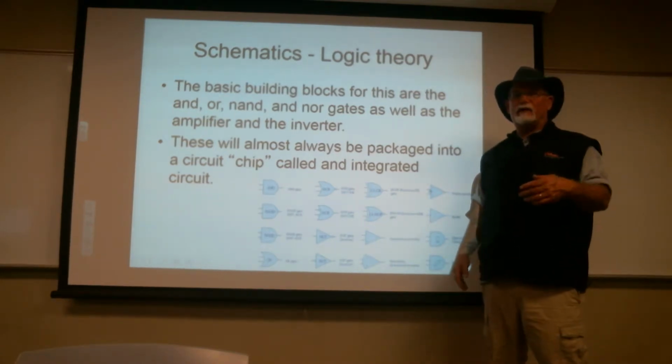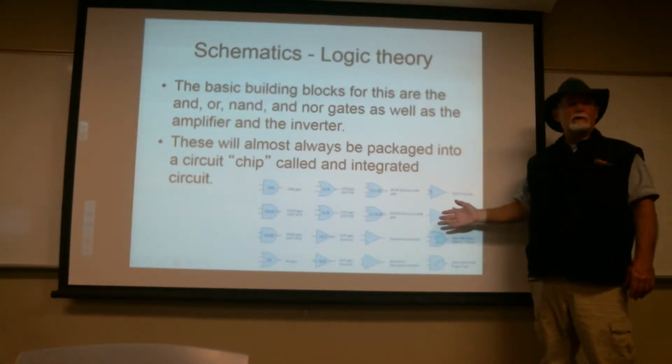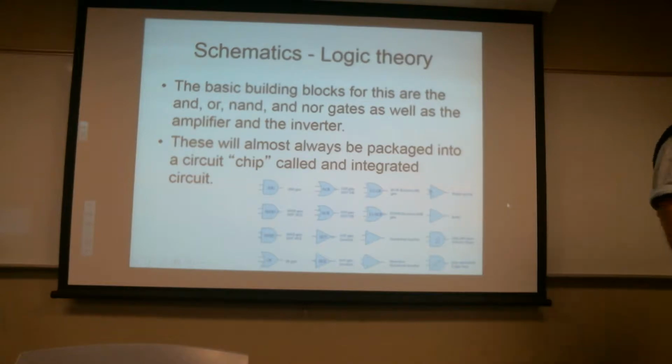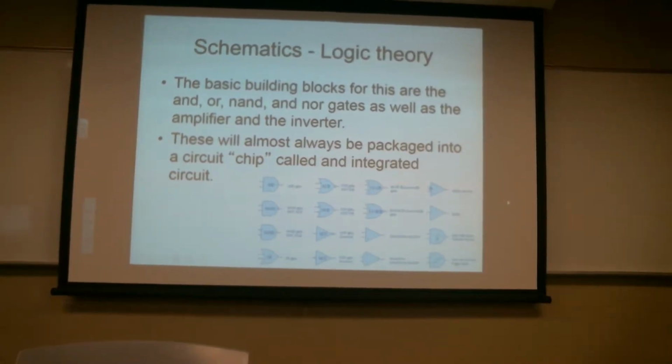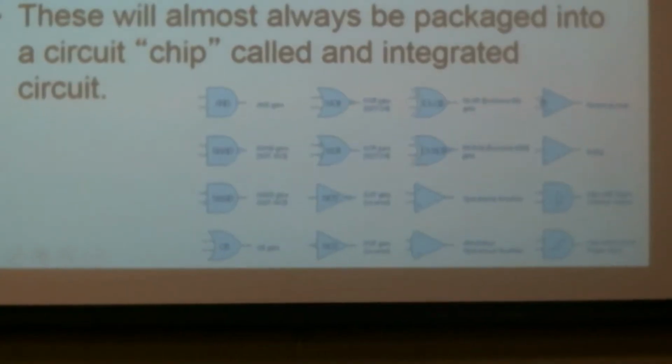So when a high comes in, a low comes out. I can also have a device that just isolates the two, commonly called a buffer. Actually, we end up using the exact same thing, just the non-inverting side of an inverter. What we're doing there is we're saying, okay, I've got some kind of an analog voltage that tends to wander a little bit. Maybe it goes from 5 to 7 volts somewhere, or 4 to 7 volts, and that's my high state. And my low state is usually half a volt up to 2.5 volts.